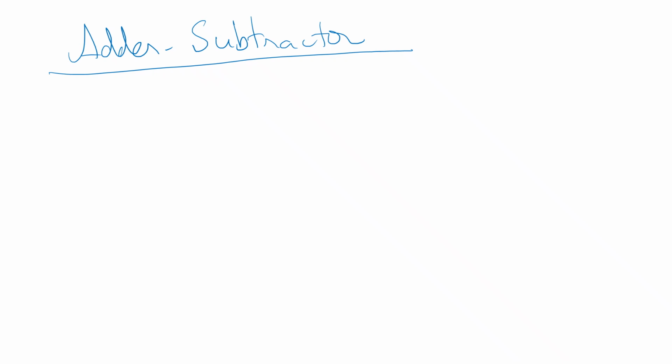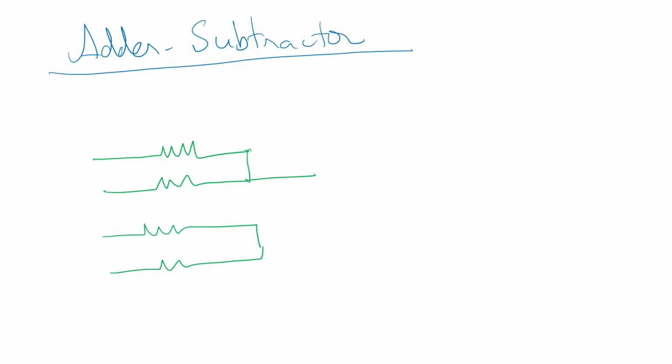We will take 4 resistors, all of equal values. 2 resistors being connected to the inverting terminal and the other 2 resistors connected to the non-inverting terminal. The feedback resistor and the input resistances are of the same values.